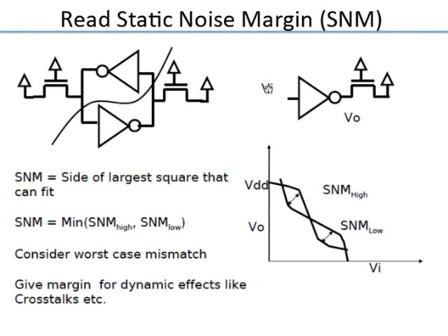So now this idea of noise margin can be quantified. What we have looked at so far is just an intuitive understanding as to why you have a problem, that the zero node bumps up and, if it bumps up too much, it causes a flipping of the cell. Now the way you quantitatively analyze this noise margin is to do a DC transfer curve. This is something we looked at very early, in the first or second lecture, I think.